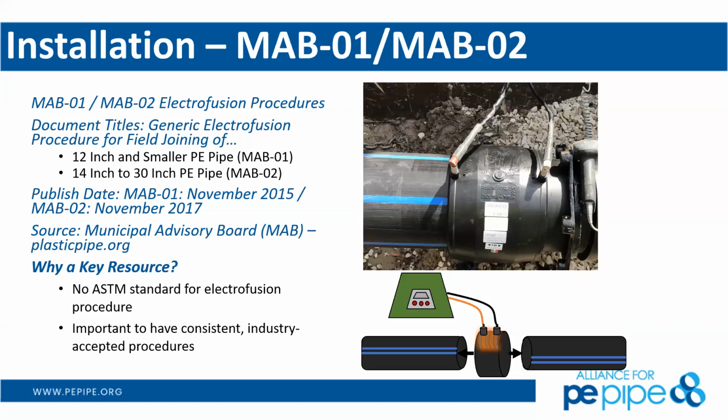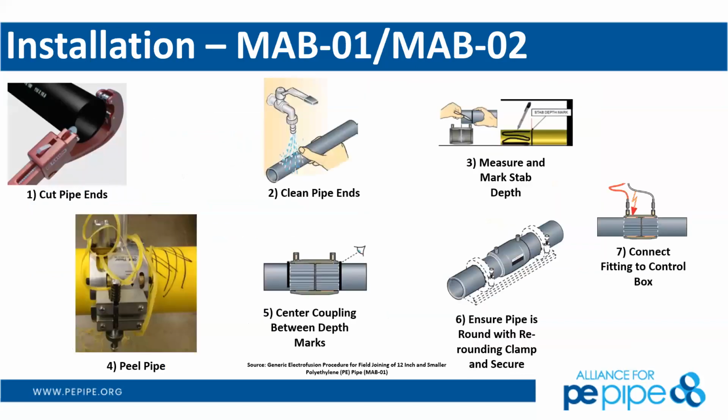But yes, for the electrofusion, you have a little bit more prep. I consider butt fusion the number one. Electrofusion for connecting polyethylene would definitely be the number 2 methodology. You're prepping that pipe very similar to the butt fusion, except you're scraping instead of facing the ends of the pipe. You get a square cut end.